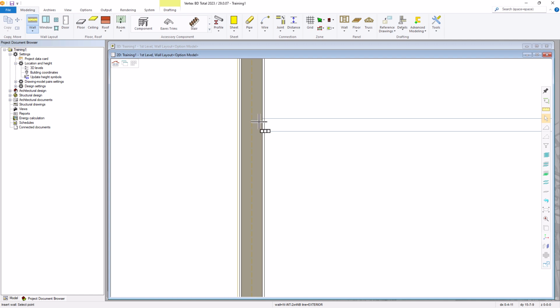I'll zoom in. I'm going to select either side, doesn't really matter. I'm going to select this top side, and if I lock in the horizontal with the U key, my wall is lined up correctly. If you find that your wall is not lined up correctly, you can right click again and use the placement icons to see if it's lined up. Obviously that one is not. Just right click to bring up that menu and keep setting it until you finally get the correct lineup that you need.